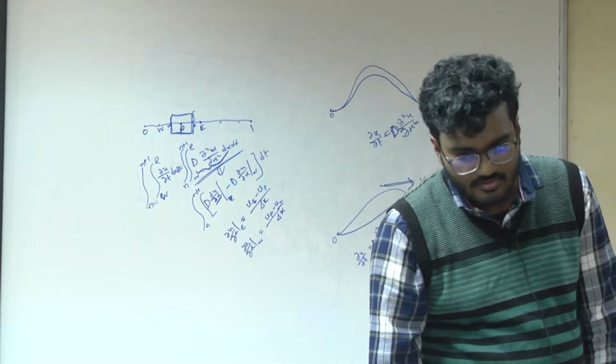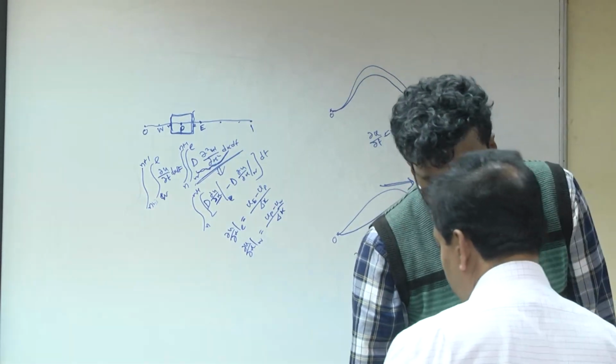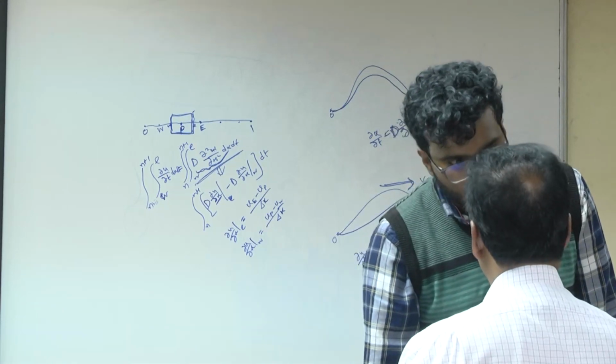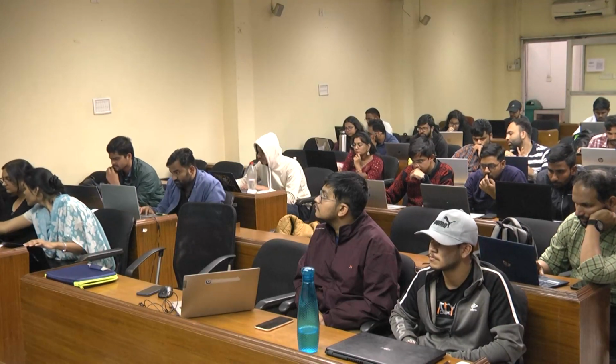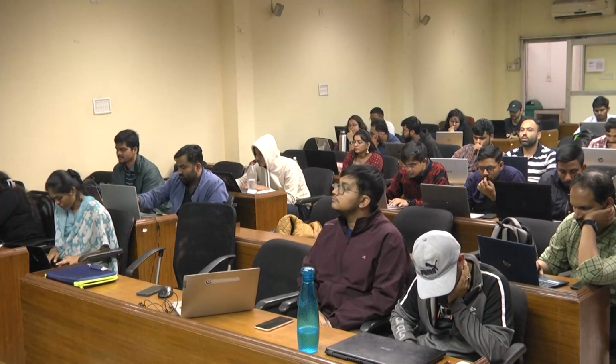Sir, what boundary condition should we give next? What kind of boundary flux condition should we use? Actually for the Gaussian pulse, both ends are fixed only. Yeah. So we can ask them to change the convection velocity and plot, compare the two. I think that's a good idea. Compare the convection velocities together. So instead of 1, put 0.5 and 1.5 or 2 and see the results.